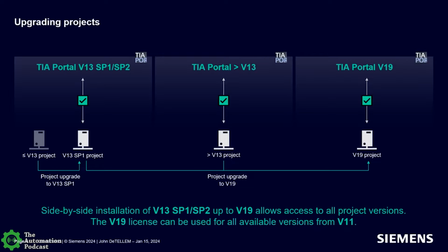Another thing that comes up a lot of times with customers when we do this new release of v19 is there's new hardware. So the PLC will have a new release of a hardware platform, 3.1 and firmware 3.1, and you won't find that in your v17 software, but it is compatible.